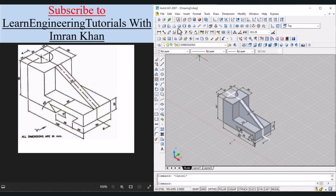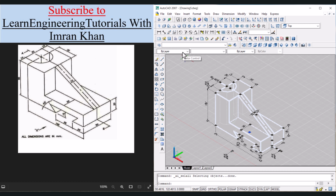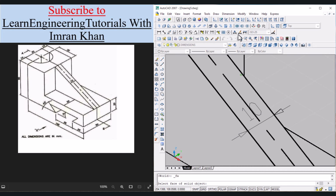So we have to go to this 3D hidden visual style, and from here we can see that in this view all the lines should be black. So we have to select all, go to this property first block, click on white, press escape. Now the object looks complete. We have to move this 10. So for that we'll select this face UCS, click on this face, click on accept, click on this 10 now, and now we can move it wherever we want.